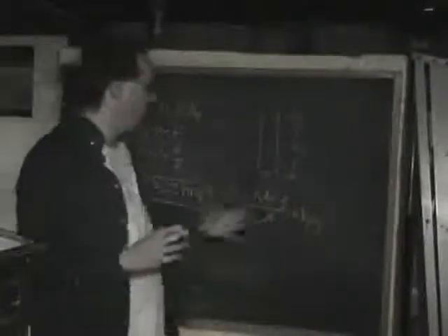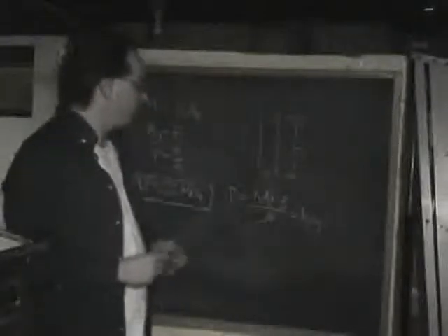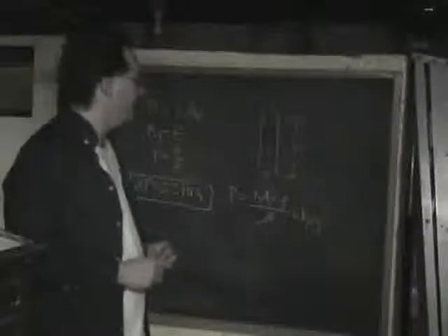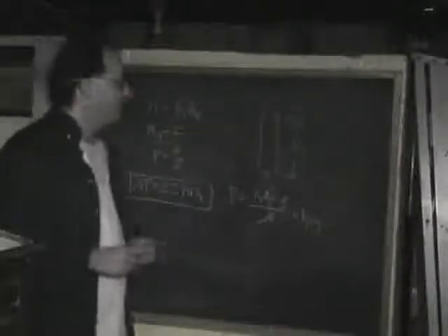So we collect all these terms together, is going to be H A rho, that's the mass, times the force due to gravity, G, over the area. Well, we immediately see that the area terms cancel, and we're left with H rho G for the pressure exerted by a column of fluid of constant density under the influence of gravity at a certain height h. Now, it's relatively easy to just toss some numbers in there and get some rough figures.